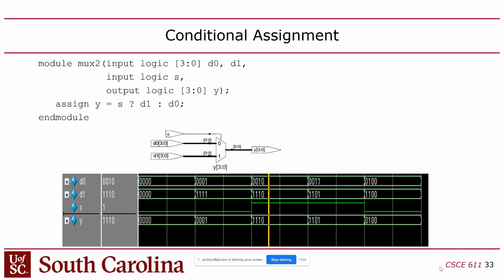Now you might say, wait a second, I thought you said this thing should be hierarchical. Well, actually, I guess I answer my own question. This whole module is just a mux. But the question is, would you actually create a module for the mux? Probably not. This is where you take it too far, right? If you take the hierarchy too far. In practice, if you want to put a mux in your code, you usually just put that line in there. You don't actually instantiate a mux module. Although that's what they did here.